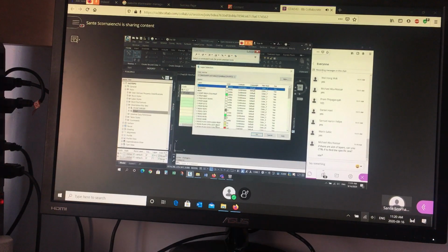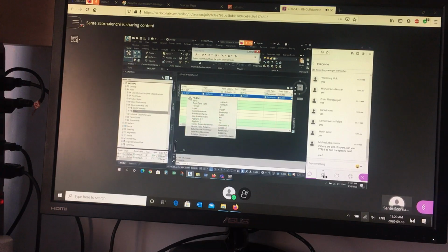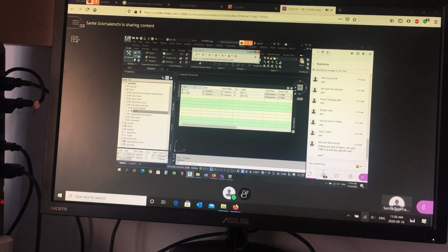Then choose the layer and find it. Again, if it's not on the list, you can use this button here to create the layer. So I'm going to use P-EOP. That's the layer. So if your description is T-EOP, then you go on a layer called P-EOP. Those are the 2 columns you need to concern yourself with. Make sure you put in the code with the asterisk at the beginning and at the end, and make sure you put the layer name. If it starts with a T in the file, you want the layer to begin with a P, because my company standard is to put points on P- layers, even though the surveyor has T- for topo.